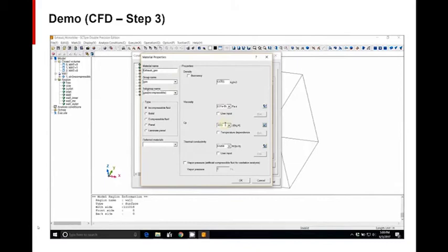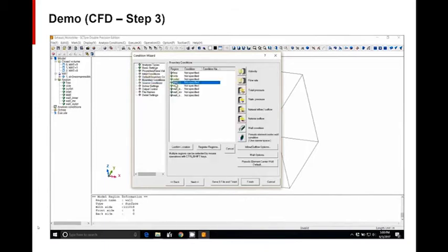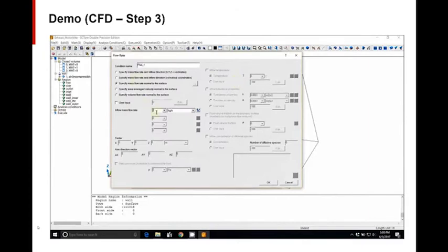And then under the solver settings, we can tighten the convergence criteria between the time steps, where we reduce the relative error to 1e-6 and increase the number of iterations. In addition to this, we also need to make sure that we use a second-order implicit scheme for the time derivative term to calculate the results a little bit more accurately.